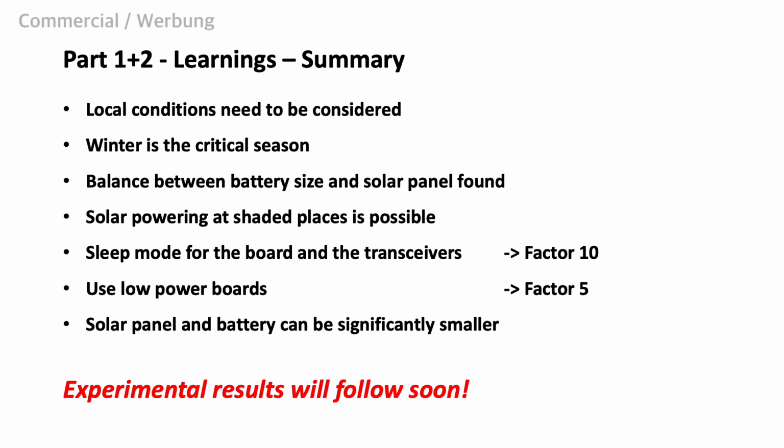We briefly recap the learnings of part 2 now. Our tool helps to create a solid design for a solar generator that is overcoming all seasons and exceptional variations. Depending on the power consumption, the size of the solar panels and the size of the batteries can be an issue, especially when these are limited by the budget. However, these problems are blown away if you are able to use the deep sleep mode, especially with low power boards.